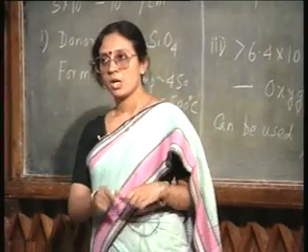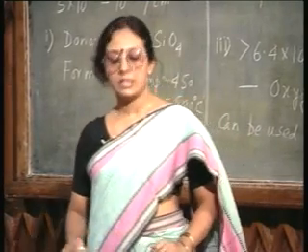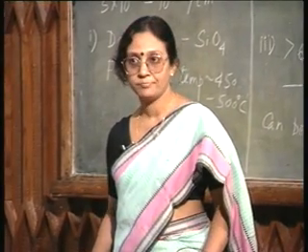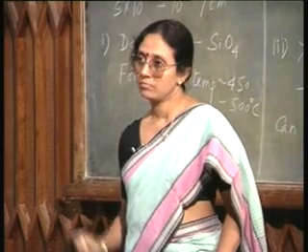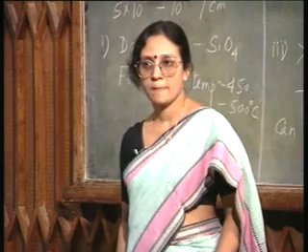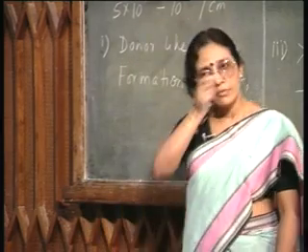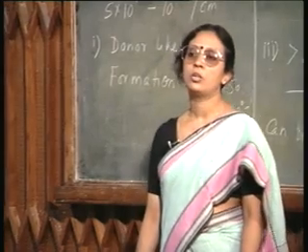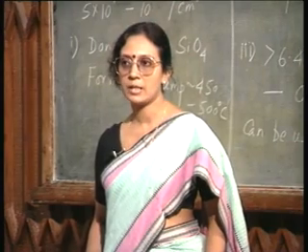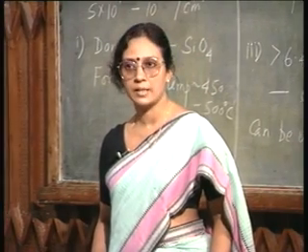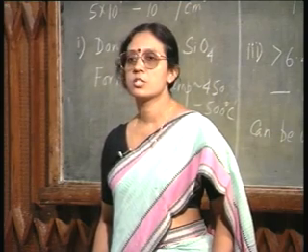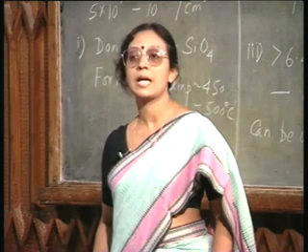So, oxygen concentration in the Czochralski grown crystal is quite a problem. It has three effects, some of them are beneficial, some of them are not so. Particularly if you are very keen on the performance of the device, like for example, if you are making power devices where the breakdown voltage needs to be very high and the leakage current has to be very low, then this oxygen concentration in silicon may not be acceptable,